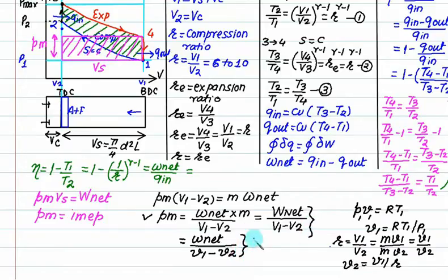In both cases, the answer will come in pascals if the work is in joules per kg and specific volume in meter cube per kg, or the total work in joules and the volume in meter cube. Later on you can convert into bar. The higher the value of mean effective pressure, the more powerful the engine will be. So engines are basically compared with Pm, not with displacement.